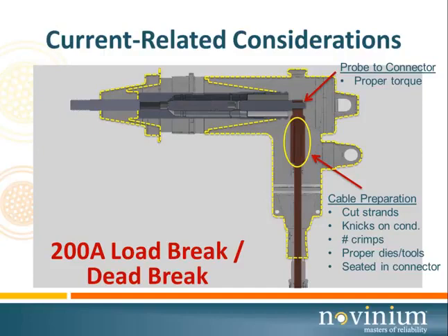And also the 200 amp dead break connectors have a throwaway wrench similar to that. Now, there are tools on the market that have built-in torque limiters on them. That's also another way to do it.